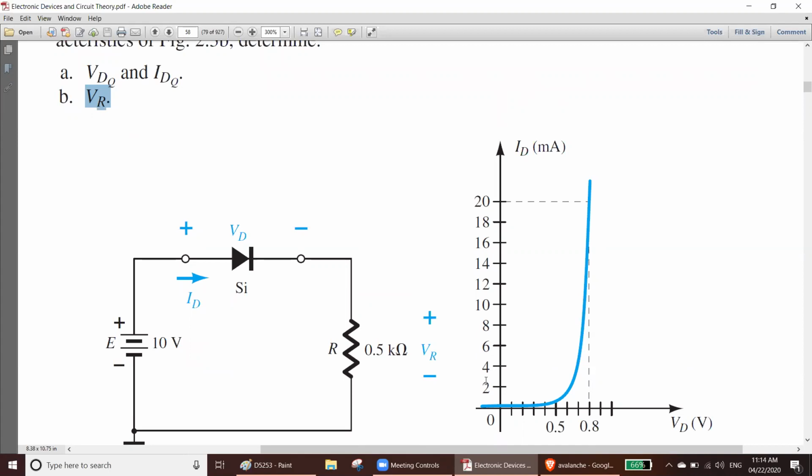Now, always remember, this is a characteristics curve. It will vary depending on the resistor and the voltage source you are having. So you need to draw a load line and find where your diode is working. What is the working point of your diode? Since your voltage is fixed and your resistance is fixed, it will be somewhere here, not everywhere.